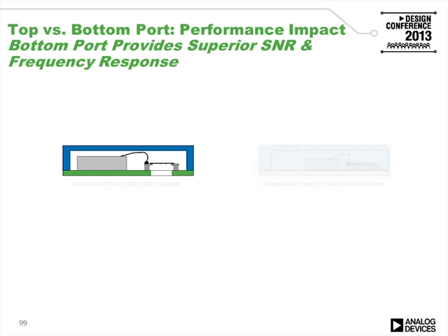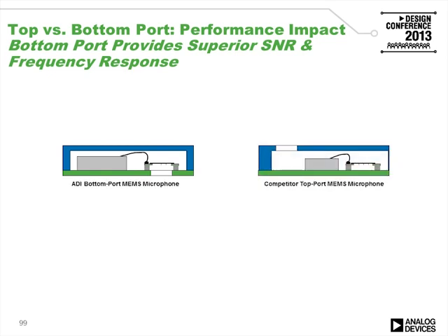There are MEMS microphones out there that have a top port configuration, and we often get asked the question, well, why don't you also make a top port microphone? Well, in our microphones, we're striving for high performance, and the bottom port configuration enables us to achieve a superior SNR, but more significantly, a superior frequency response as compared to the top port microphone.